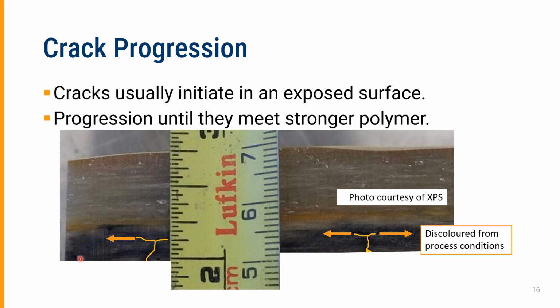This is actually from a duct exposed to sulfur dioxide off gas from a smelter. And the cracks form in these embrittled areas on the inner surface. They're exposed to the highest temperatures and the greatest chemical attack from sulfur dioxide, which is relatively benign for FRP.